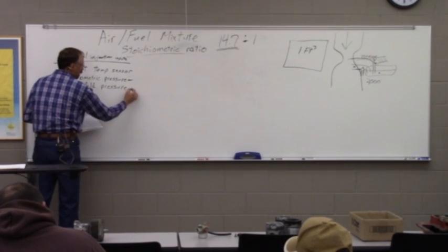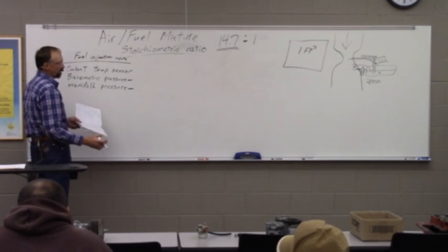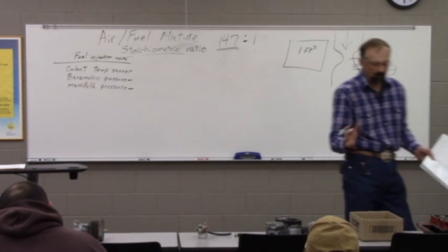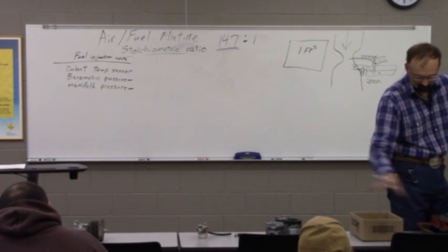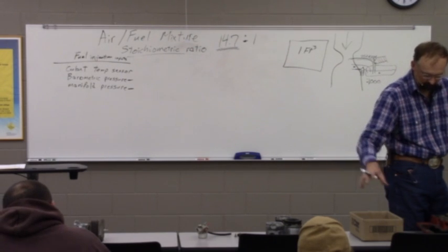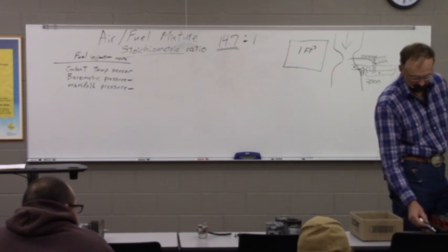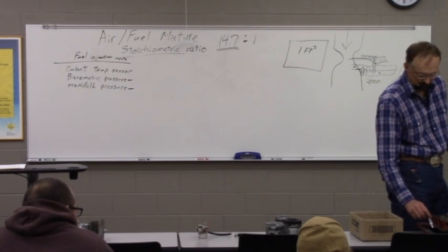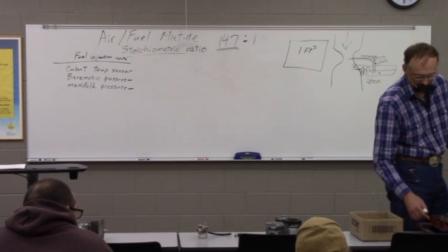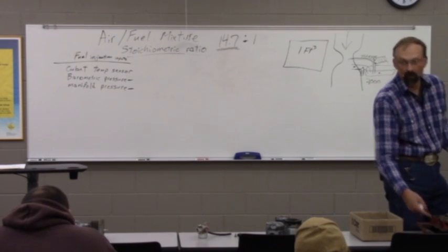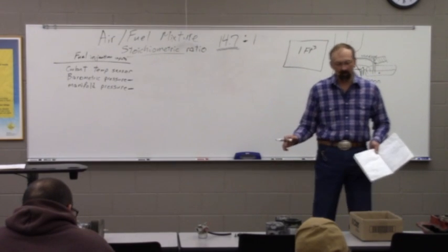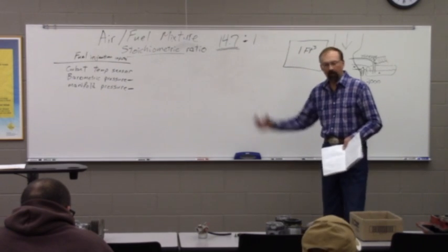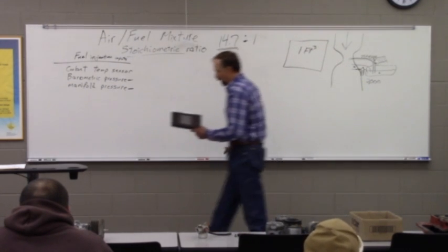This one's the pressure in the manifold of the engine. So what we're talking about there is the intake manifold. So there's plumbing here to get from the air filter in through other devices and into these runners that are going right into the intake valve. And many of these systems will measure the air pressure inside this manifold. So they'll have a comparison of what the atmospheric is and what the pressure is right in there just before it goes into the cylinders.